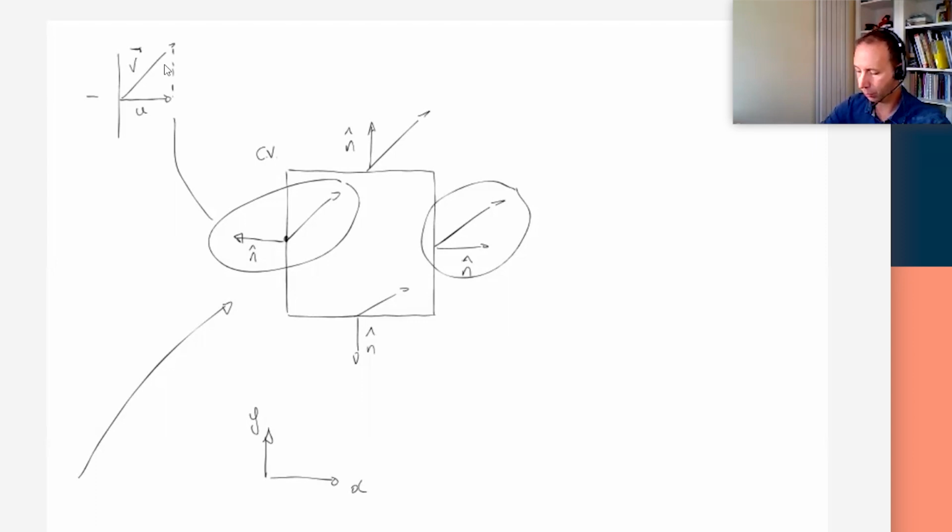So we just take the x component of the velocity vector, and that u will be effectively minus v scalar product n, right? Why minus? Because the vector is going in the opposite direction. The velocity vector v here is going in the opposite direction to the outward normal. Outward means it points out of the control volume. So if we take a scalar product of these two, it will give you a negative value because they point in the opposite direction. If you want just the velocity component x, you see v points in the positive x. Here it points in the positive x as well.